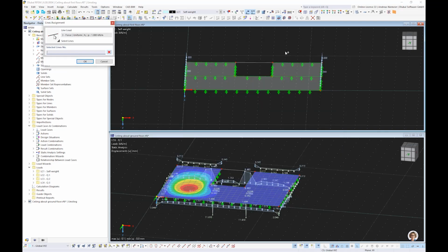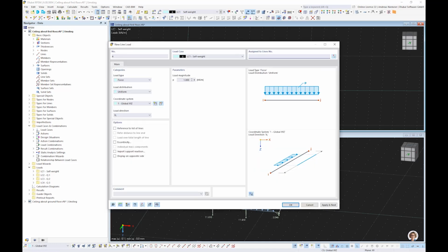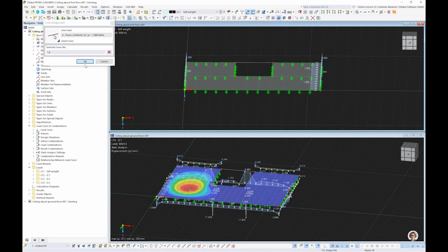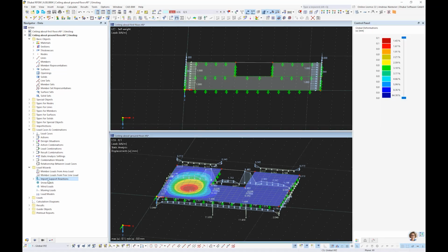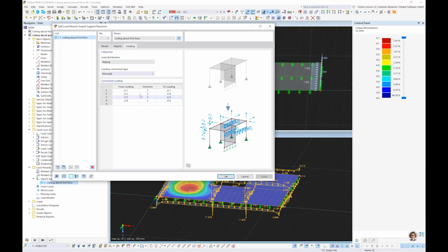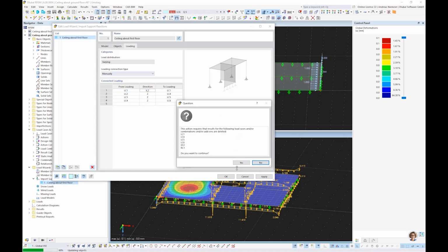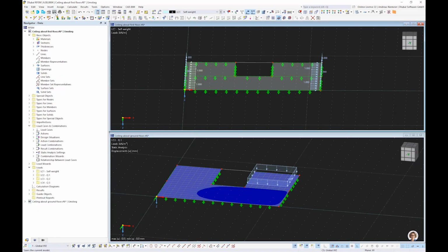Let's use here 1, and let's use here -1, so that we have some roof load effect. And you specify now in the blower model, in the wizard, hey program, please use for the permanent state not only Z direction, but also X component, and confirm it. The program wants to delete results. Yes, we have to save, clear.